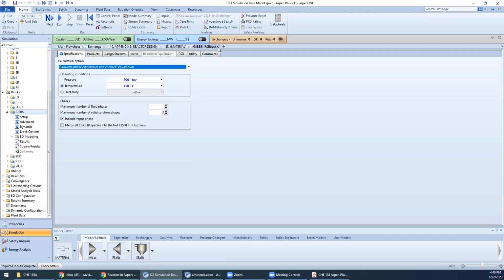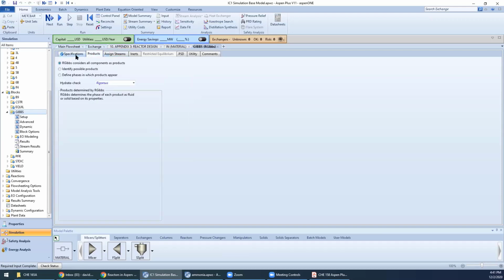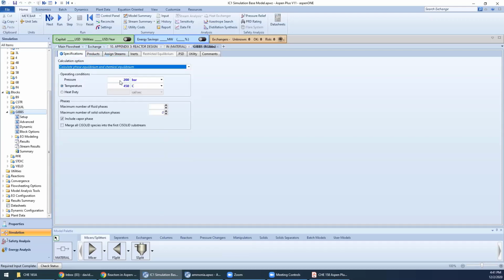And so that is the difference in those two streams to allow that unit operation to converge. For this, having 0 as your approach is pretty standard for the reactors because it's going to be governed by the kinetics or the thermodynamics that are occurring based on the use of the databases. Okay, thank you.